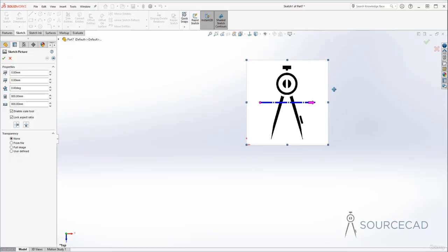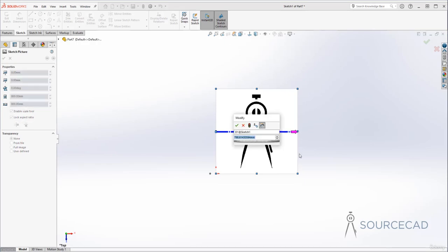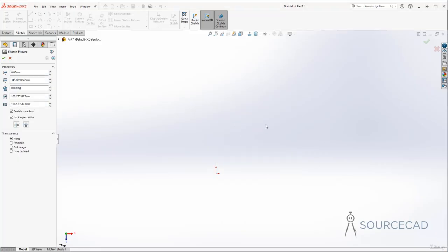Now we can resize this picture, and that's the first thing you should do here. So currently this size is completely random. We don't know the length or width of this image. In this case, I'll move this scale slider and I'll just resize it properly. So I'll just move it right here, and then I'm just going to move this arrow up to this point. All right, now this length should be equal to 100 units. So I'll just type 100 here. I'll click OK, and there we are.